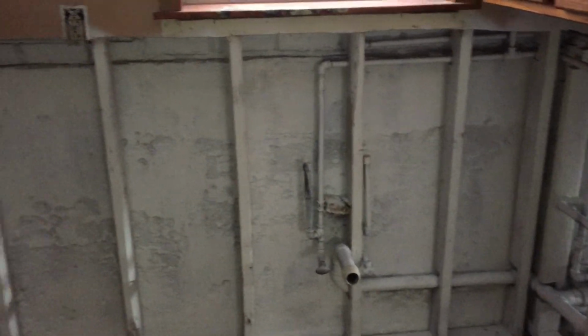So you'll see here that the drywall has been removed, and the insulation has been removed. We get down to the semi-porous materials, the wood framing members, and the non-porous materials like the concrete foundation walls. We then scrub them down with that biocide product, again a product used to kill mold on contact, and physically agitate the mold spores from those surfaces. We use HEPA vacuums during the process to make sure everything is cleaned thoroughly, and then we put on that white acrylic-based mold-resistant coating. The whole time we do the project, we run the air scrubbers to get that air clean.